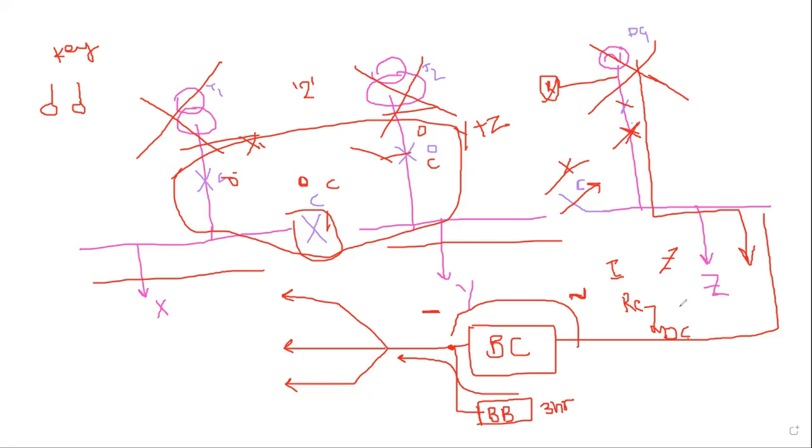If the DG set or the cable or the battery charger, whatever it may be, any one of them fails, then the battery bank will finally come in and feed all the emergency loads. Emergency loads, in the sense, are only those related to control and protection. If you want to place the lights also, it's your wish. You have to consider how you are designing and how many loads you are putting on the battery bank. So this is the scheme.